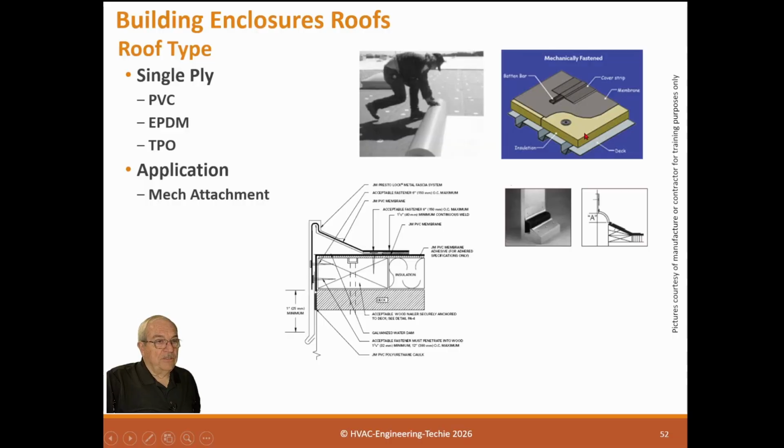I have seen many jobs where the slope goes to where a drain was going to be but didn't get there, or goes away to someplace else where there's no drain. It's really poor. Or it doesn't actually slope to the drain. So you need to check all that out. The other thing that's important: you'll see the roofing material go down, and it's actually adhered with a special kind of nail that has a little top on it. It does that because this must be adhered. Normally we see glue adhered, but it must be adhered.